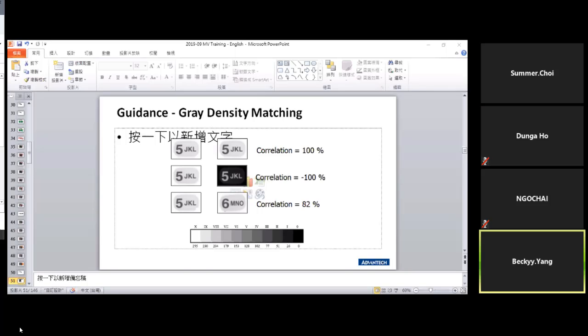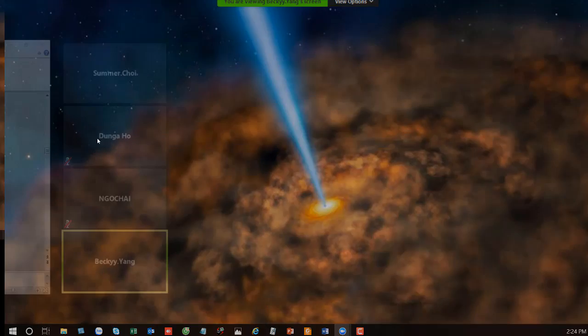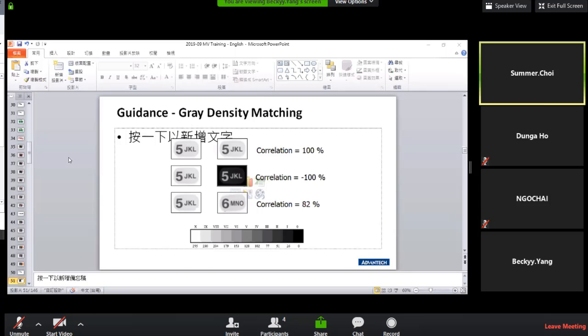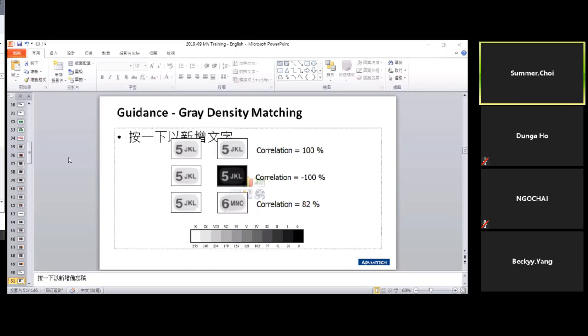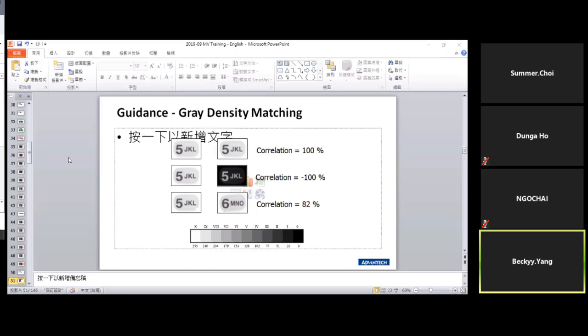Okay. So we will see the ROI when we drop it on your object. You can choose all of your object, and the ROI will be correct. Then you press set, and the model will be finished. Then we can see right here the result: the number of matches shows 1, so it's correct.